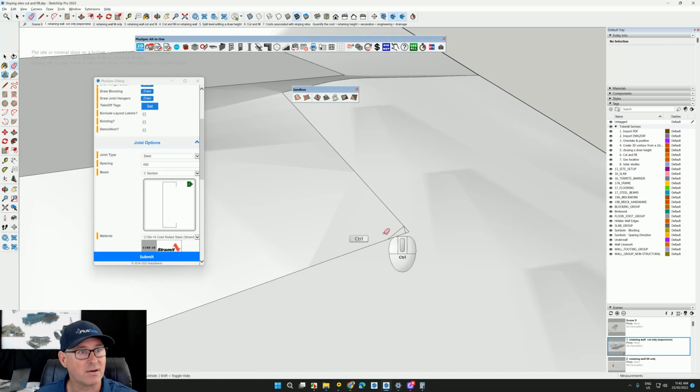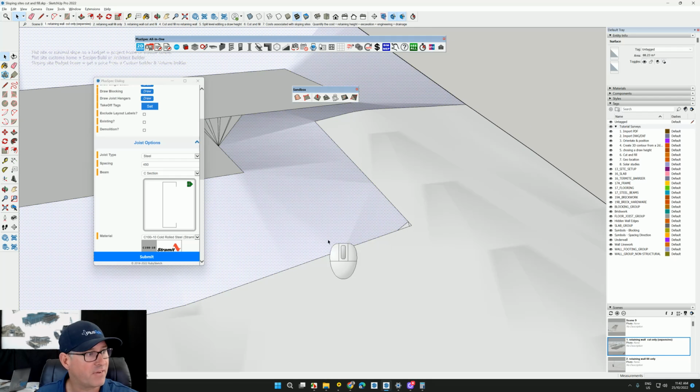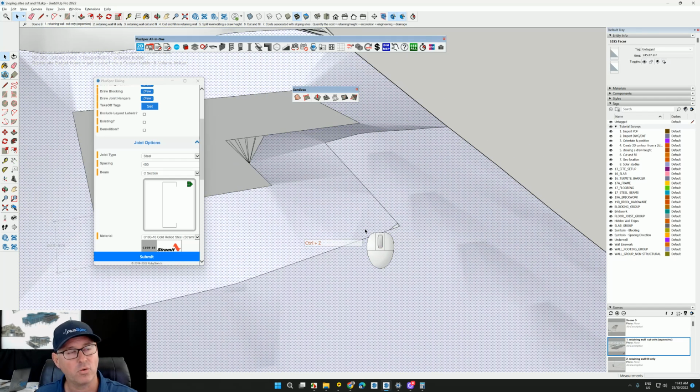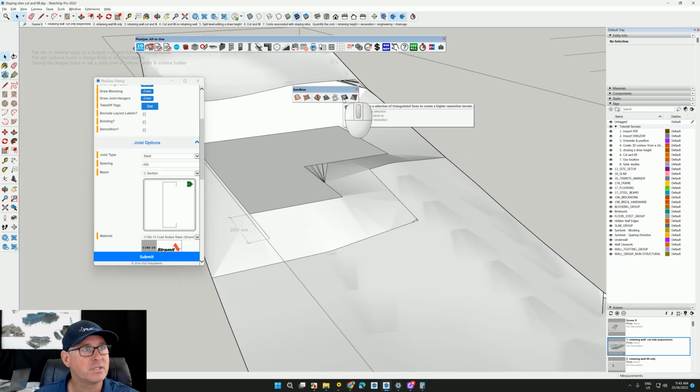You'll notice if I select that face, all the way until I smooth, it made that as one face. If I made a mistake when I did it, erase again, now I would have one full face. That might help you when you're adjusting terrain. You'll also notice there are other items inside of here that enable us to do it. I can add edges to a selected triangle, and you can just mess around with these. The help is down the bottom right hand side, so you can choose that as you please.